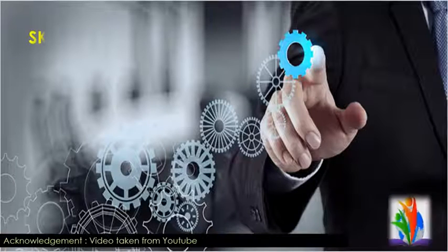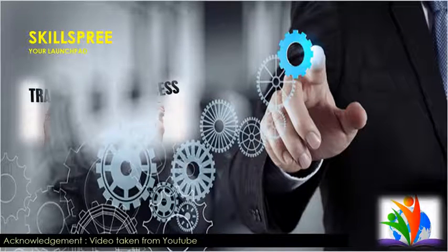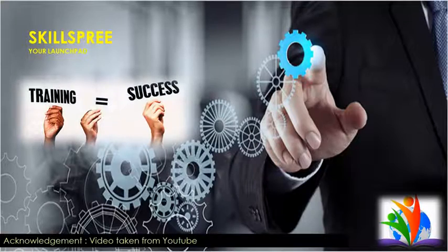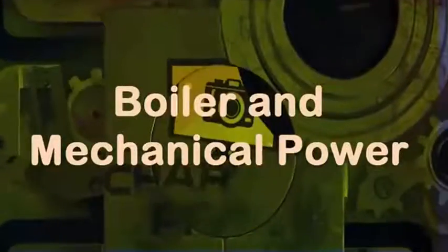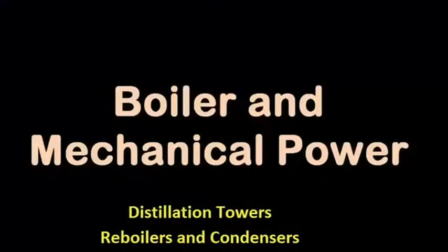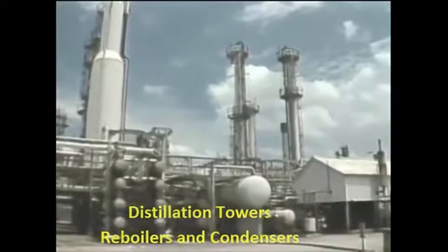Distillation towers are designed in a variety of ways to meet the demands of particular applications. A distillation tower, or column, can be categorized by the number of products that leave the tower. Two common types of towers that are identified this way are binary towers and multi-draw towers. A binary tower separates a feed into two products. For this reason, you may also hear a binary tower referred to as a two-product tower.